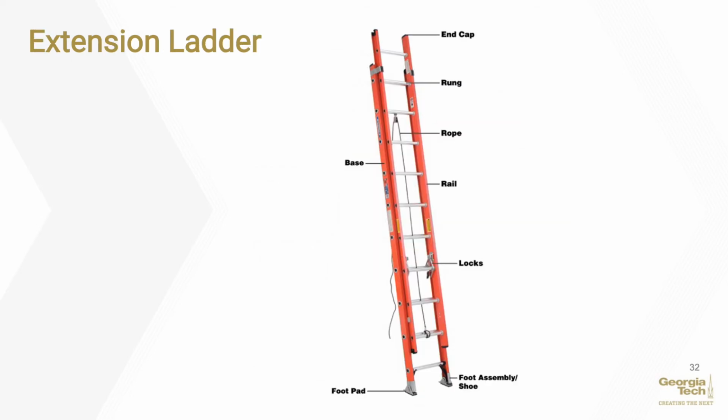Extension ladders are non-self-supporting ladders. Extend side rails of portable ladders 3 feet above the upper landing surface. When extension is not possible, secure the ladder and provide a grasping device to assist workers in mounting or dismounting the ladder. A ladder extension must not deflect under a load that would cause the ladder to slip off its support. Keep ladders free of oil, grease, and other slippery substances.